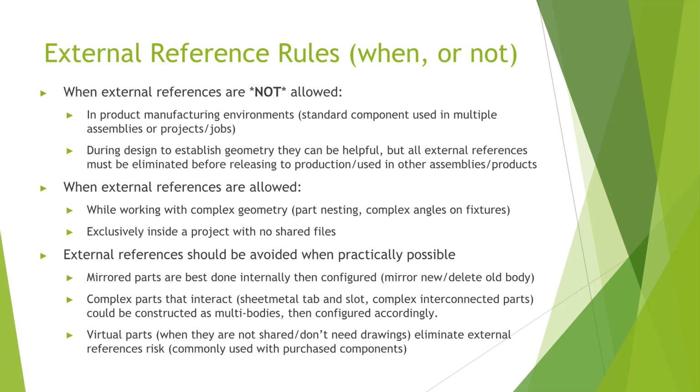External references. You do not use external references in a product environment. So if I was designing tables and I had to design the caster and that caster goes on 50 different tables, having external references in that caster is a very bad thing. Because the one table that I put that caster on would work just fine. But then the second table I put that caster on, that caster is going to reference the first table, and you're going to have this massive spider web of references. So if you're a product designer, you do not use external references.